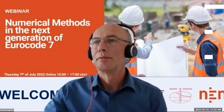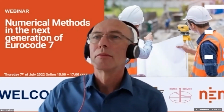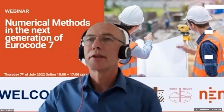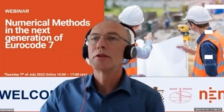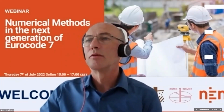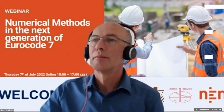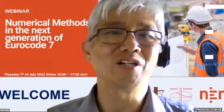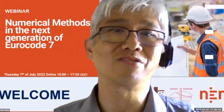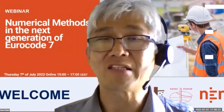Okay, thank you. Then next question: Eurocode provides factors on soil properties, but it doesn't describe factors for Young's modulus. Can you please explain what factors to be taken in DA1C1 and DA1C2 on soil Young's modulus? I mean, the factor that we apply is only on the strength parameters, not even the density. So it's only cohesion and friction.